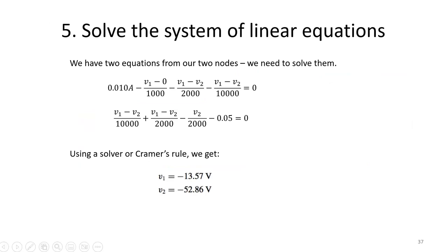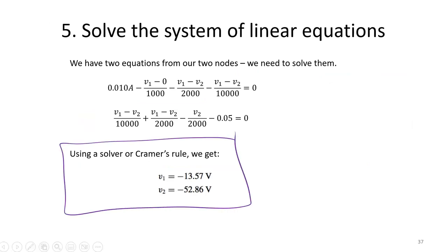So now all that's left is to solve our systems of equations, and once we've done that, we will actually determine V1 and V2. Remember, these are determined relative to our 0-volt reference node. So don't panic if the voltages are negative here. That simply means that V1 and V2 are sitting at a lower voltage relative to node 3.